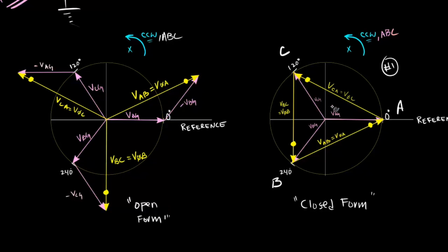And we clearly see that it doesn't, right? The triangle actually represents the line-to-line voltage of the delta transformer connection, but that is also equal to the winding voltage, right? But our line-to-ground voltages are actually these inner phasors. That's one of the problems for this closed form, that it makes us think differently when we first visually inspect it. So the second problem for this closed form phasor diagram is that when we look at this, we think that the origin represents the neutral or the ground.